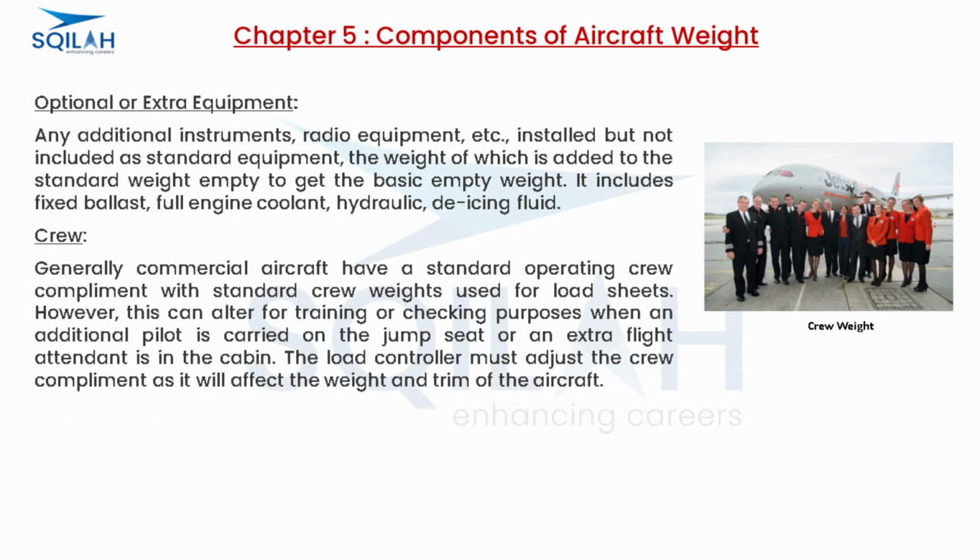Optional or extra equipment. Any additional instruments, radio equipment, etc., installed but not included as standard equipment, the weight of which is added to the standard weight empty to get the basic empty weight. It includes fixed ballast, full engine coolant, hydraulic, and de-icing fluid.